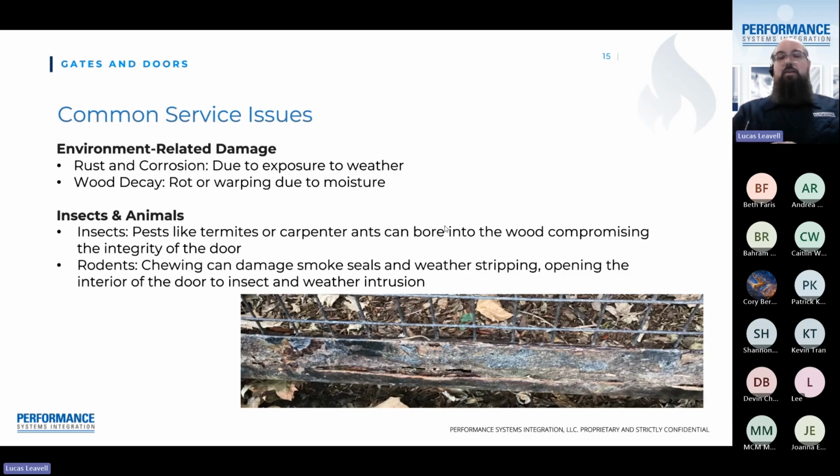And nothing is greater at causing corrosion than environment, specifically outdoors. Pictured here is the bottom of a fence that the irrigation sprinklers for their landscaping were spraying upon. That spraying eventually eroded away the enamel coating and allowed the metal underneath to begin to rust. And this is just a steel piece of metal. Well, that steel eventually corroded, and as the corrosion starts, it does not stop. You can remove the corroded component, you can paint over it, you can scrub it off, but it will always come back.